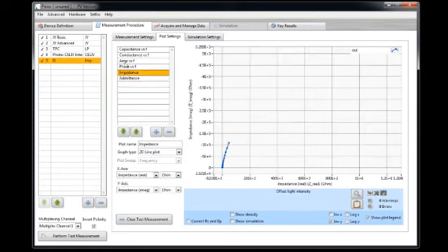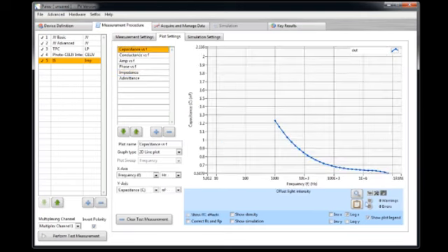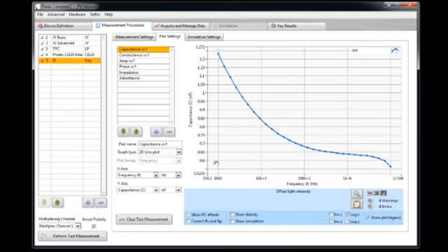Now you can choose between different ways of plotting impedance spectroscopy data. Very common is the Cole-Cole plot, or what is often used is to plot the capacitance versus the frequency. So here we see the frequency and here the capacitance, where this is probably the geometrical capacitance that is decreasing here due to the series resistance, and towards lower frequencies increasing probably due to traps.